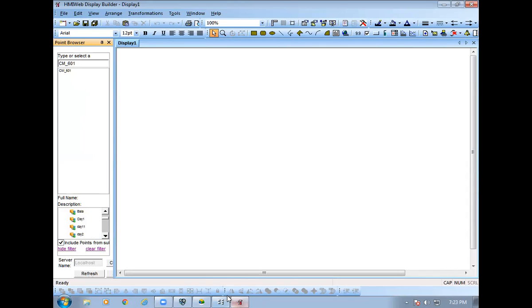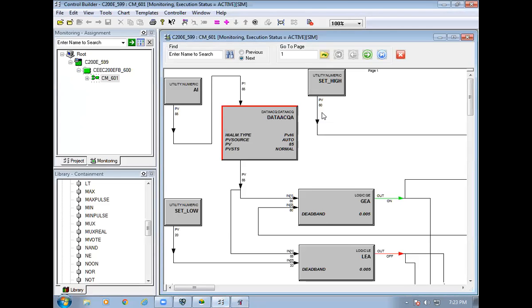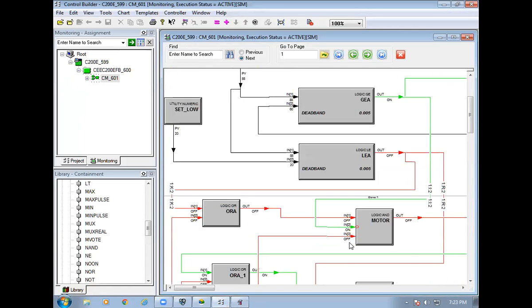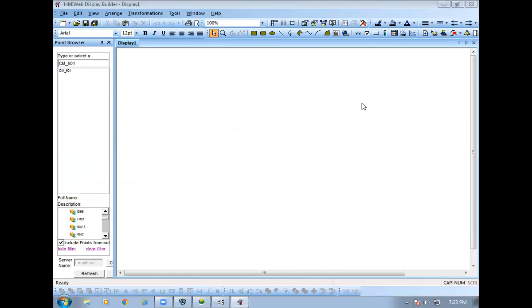So now after that, here you can see I have digital input and analog input. This is an analog input I'm assigning, then analog set points, then I have digital input and output here. How should I design it here now? If you're using a digital input, then we need to use a combo box from the menu bar. This is the combo box for all the digital inputs. So I'm choosing a combo box here. These two combo boxes I'm going to make for start and stop.